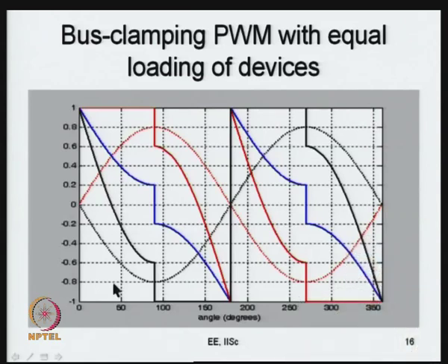Because it is conducting, there is a certain amount of loss, heat is being dissipated now, and this heat is going to increase the temperature, but there is a delay in the junction temperature rise. The junction temperature has some safe maximum value. When the device conducts or because of switching action, the device dissipates energy. In this region the devices are switching, and on account of both switching and conduction there is some power dissipated now.